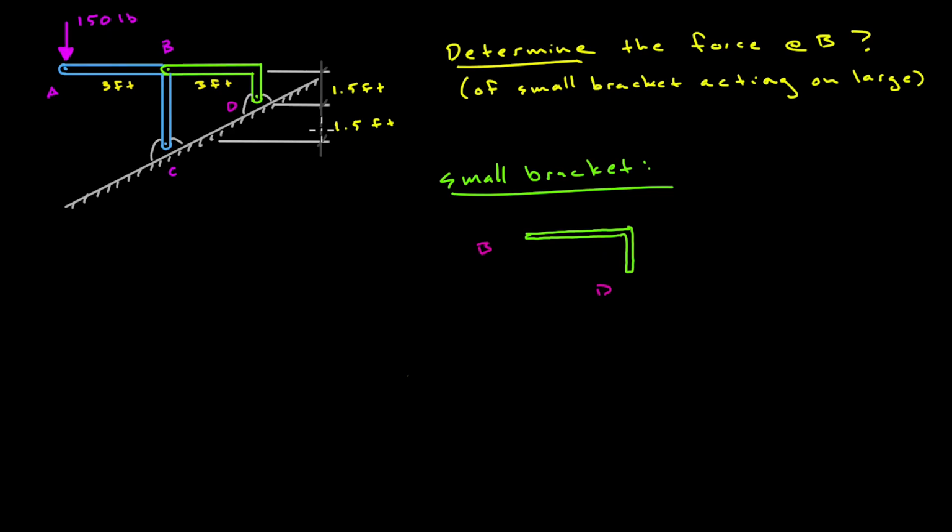So what that means is the two forces here, there's a reaction at point D, and there's a reaction at point B. There's a line that connects those two points, and so the reaction at point D and the reaction at point B, those two forces share the same line of action. Now that has to be the case because if that were not the case, there would be some residual component in a direction that's not the line of action that would contribute to some acceleration. So we relied on this concept heavily when we talked about trusses. A truss is a structure that is comprised entirely of two-force members, and so being able to leverage the property of two-force members helped tremendously with trusses, and it's also going to help us with this problem.